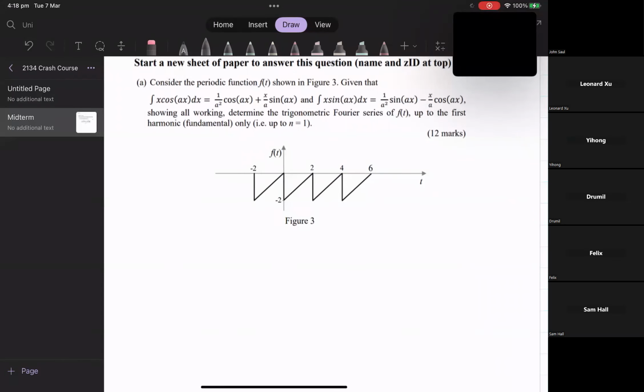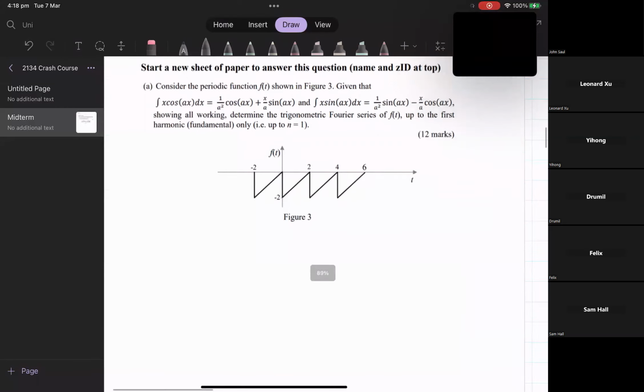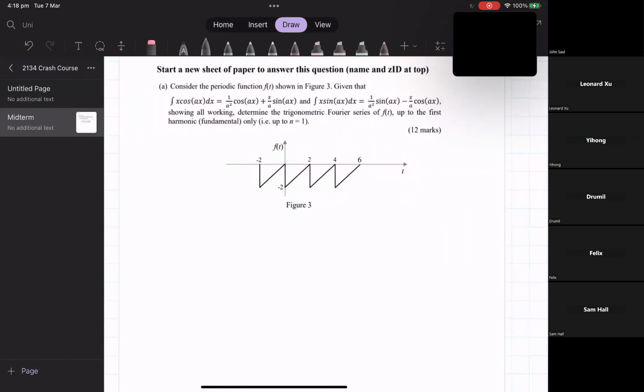Another thing that's helpful to note is whether this is an even or an odd signal. Does anybody have an idea? Yeah, it would be an odd signal. So if we flip it over the y-axis and negate it, we can see that we get the same signal, assuming we remove the DC offset. The reason we identify those two things is it gives us a shortcut in finding the coefficients. We know that since it is an odd function, there will be no coefficient for the cosines because those are even functions. So we can automatically assume that an is always equal to 0.